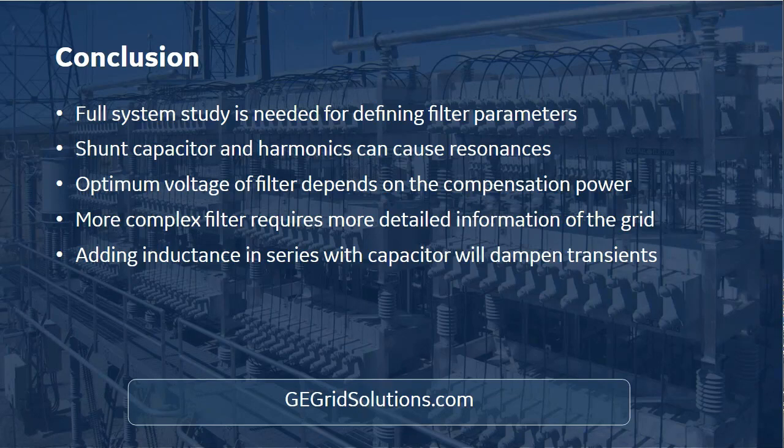But there are cases where you just need something faster than what we can provide. For example, the reconnection time for this kind of passive filter: if you switch a capacitor bank off, the time before you can switch it back on is typically something like 10 minutes. You have to wait 10 minutes so that the residual voltage in the capacitor units themselves will drop so that you can connect the capacitor bank again. So this is an issue. In some cases, you might need a faster response.